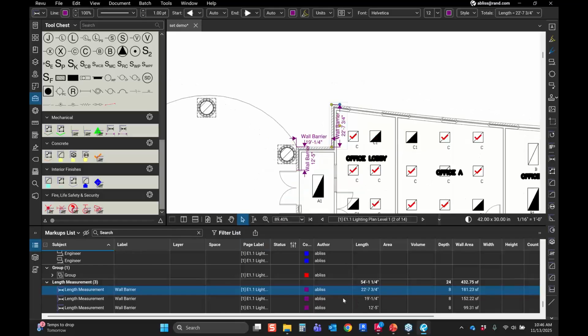You can export all of your markups to Excel with your quantity takeoffs. So these can quickly be brought out to Excel. You take those out in CSV, and then you can plug those in with your Excel skills to put pricing together. If you've got lines of conduit, you've got your quantity markers on all of your AC vents, you've got all your linear feet counted with your ductwork, you can put a price to every one of those things.